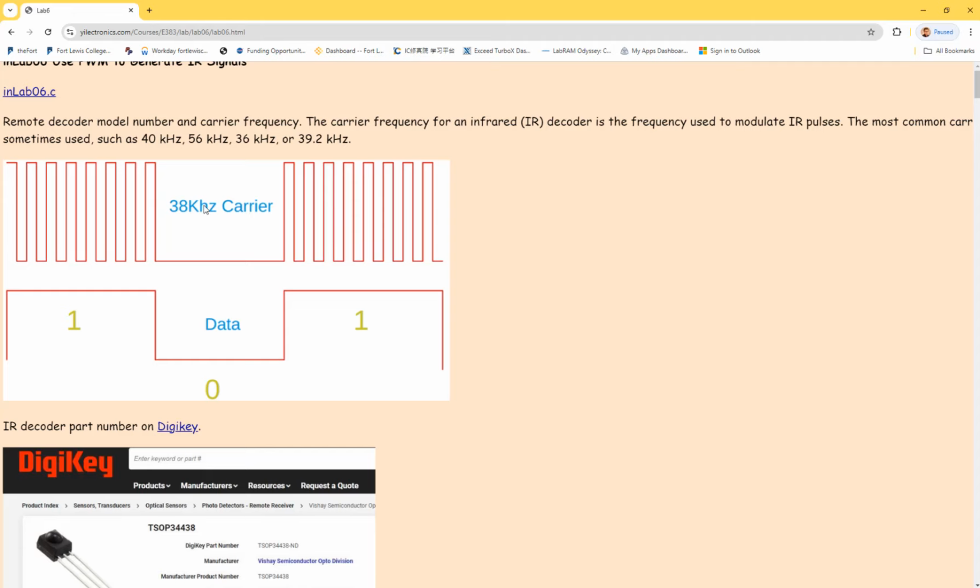It's always 38 kilohertz, and the pulses don't have a reference, just the light pulse, right? It's not like the optical signal and the electrical signal. You have a 5-volt system or servo systems, and they need to be grounded in order to communicate with each other. But optical, you throw the photons into the air. There's no reference. It's just light pulses in the air. Whenever a receiver receives it, you don't need the reference, just the light pulses. Then it will be decoded, so it's compatible between all the different systems. You don't need the reference.